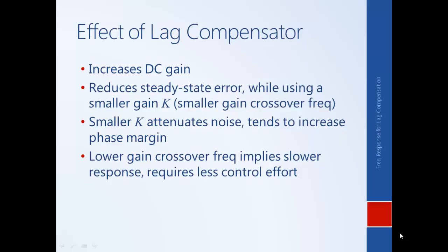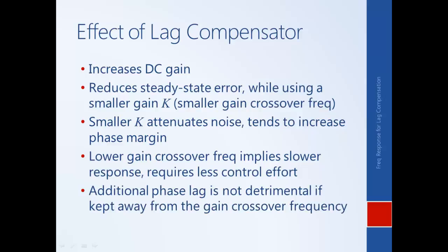It might be hard to see some of these benefits, but I'll try to point them out as we go through a more detailed example. The phase lag added by the compensator, we will attempt to keep it away from the gain crossover frequency so that it doesn't have an adverse effect on the phase margin.